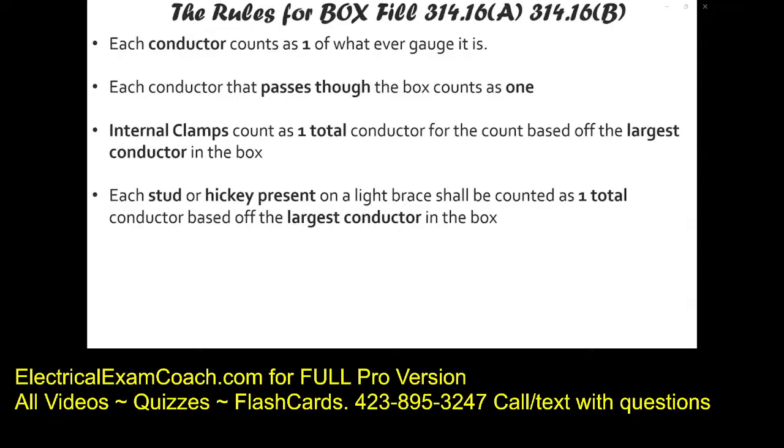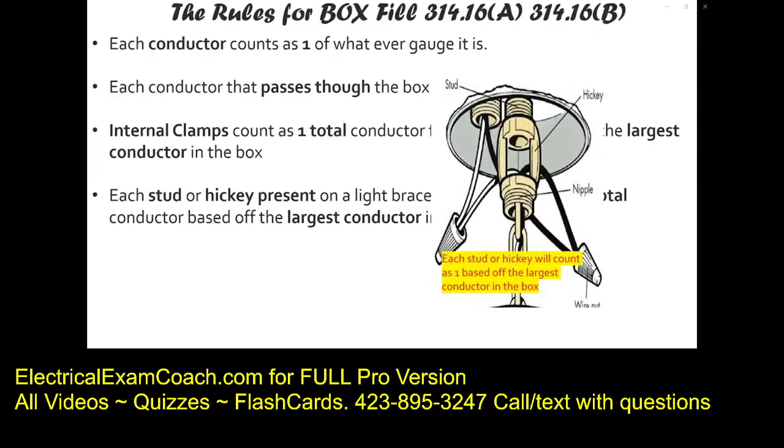Now, these are really old words, probably from the 30s if I had to imagine, but they still use them on examinations today. And this is what we're talking about. Imagine that we're hanging a chandelier. This we would call the stud or the nipple. Or, this would be the nipple, this would be a nipple. But they're calling this the stud and this a hickey. And they still use this terminology on exams today, so you definitely need to understand.